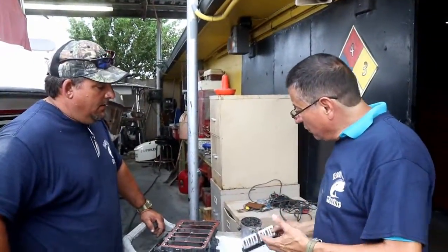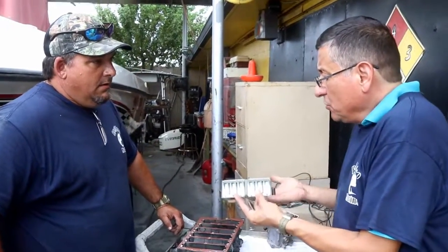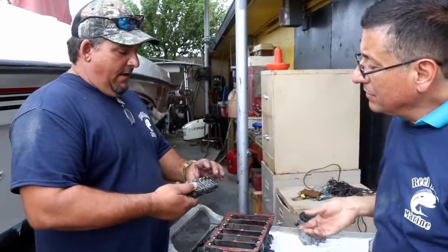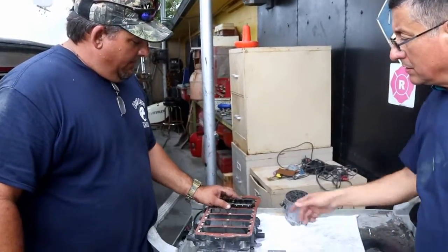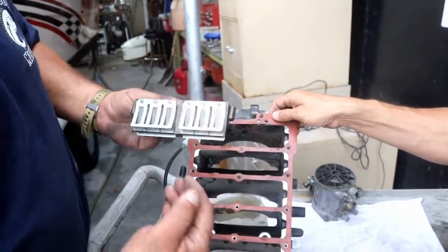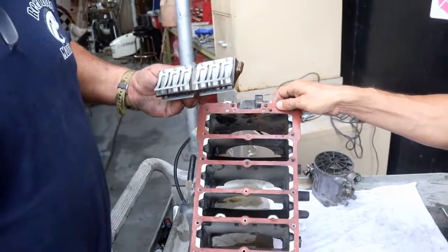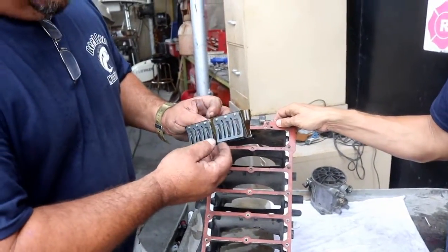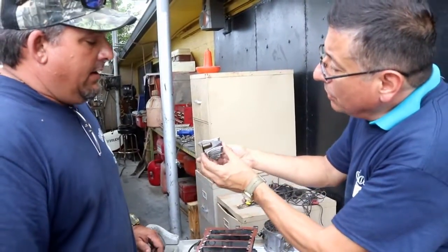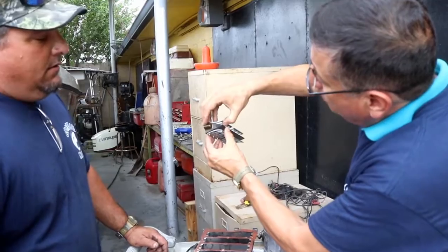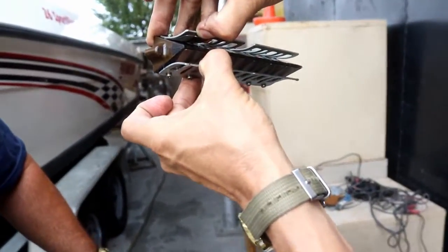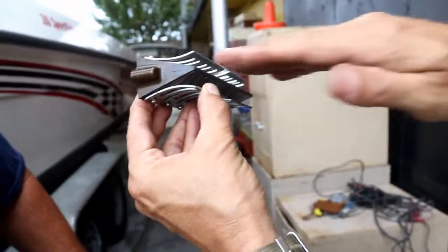Danny, what is the function of the reed valves, and how can you check if those elements are working properly? Okay, the function of the reed valves is that they go into the intake. When you have the compression stroke, it closes these valves, and when you're going on the suction side, the reed valves open to allow fuel in. Like a check, like a diode, no? Yeah, kind of like a diode, one way. In this direction, open, because those flaps open over there, and the fuel enters. And in this direction, close.